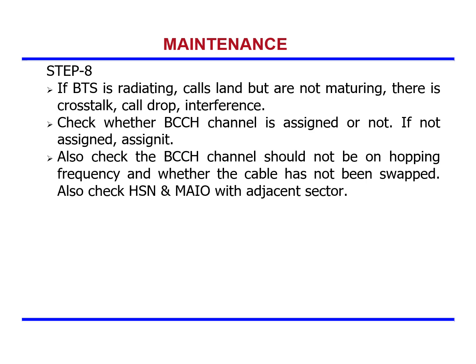Also check the BCCH channel should not be on hopping frequency and whether the cable has not been swapped. Also check HSN and MAIO with the adjacent sector. Here HSN stands for Hopping Sequence Number. MAIO stands for Mobile Allocation Index Offset.